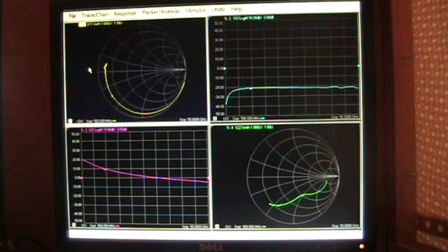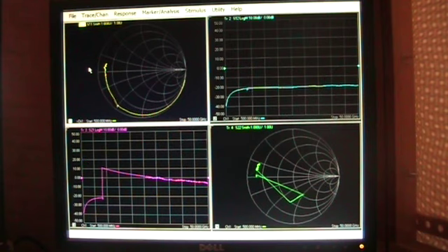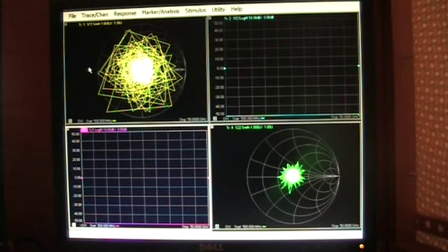I'm going to go ahead and start the controller program. And what the controller program will do, you can see it's already turned the power supply off. It will go ahead and load up the scattering parameter state file, shut the power off, and then find the bias conditions for the device. The idea is that we're going to seek a gate voltage to find a particular drain current, and then we'll record those in a table. So when we're taking noise measurements, we'll be able to sit there and work our way through that list as rapidly as possible. We're just going to keep going back to these same values regardless of the fact that the source tuner is in a different position.